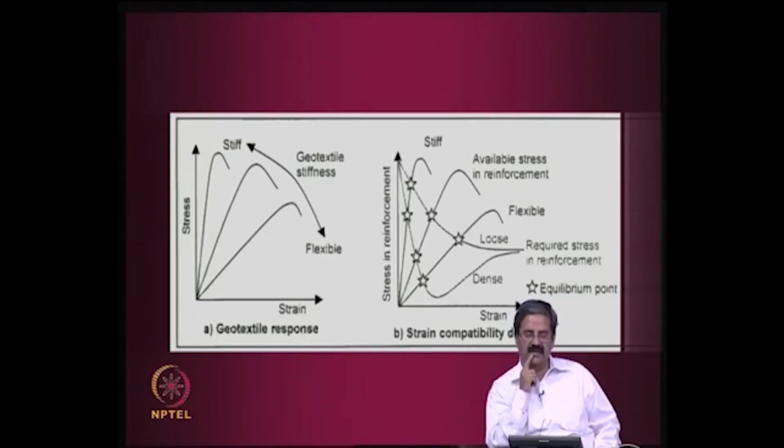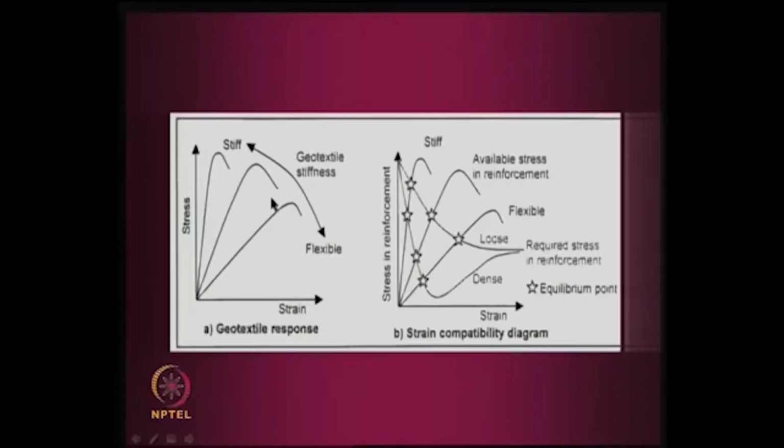Even steel also we use, like there are companies that only supply steel as a reinforcement. There are some companies which only supply geogrid as a reinforcement. There are also some companies which use a geocomposite, because sometimes you want high drainage in some applications plus reinforcement. In fact, for one of the projects which I saw, the 42-meter high wall, they used a geocomposite which acts both as a drainage material as well as a geogrid material, right. So you have this material and you also have the properties of the soils.